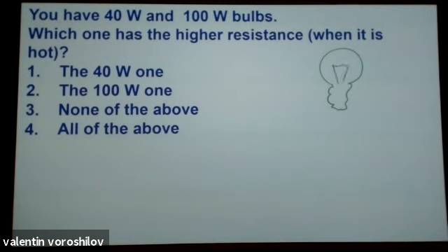And based on the power this bulb consumes, dissipates, provides, the filament may be brighter or dimmer. Well, when we turn it on, at first its temperature goes up until it reaches its highest temperature. And when temperature changes, resistance changes. Normally it actually increases, because higher temperature means higher velocity for atoms moving, so more collisions, harder to travel through. So operating resistance depends on the temperature.